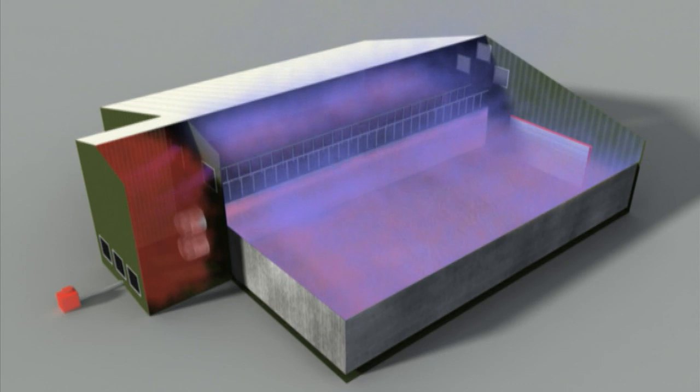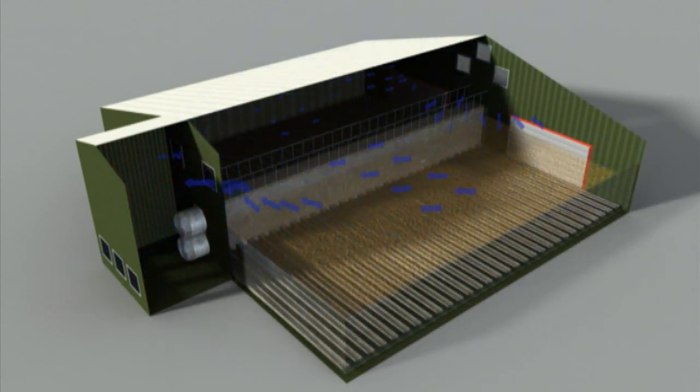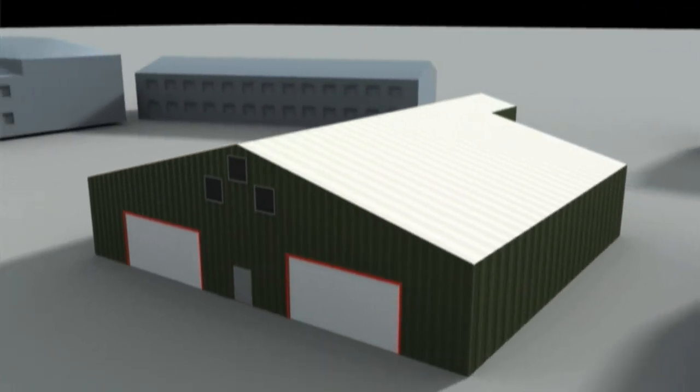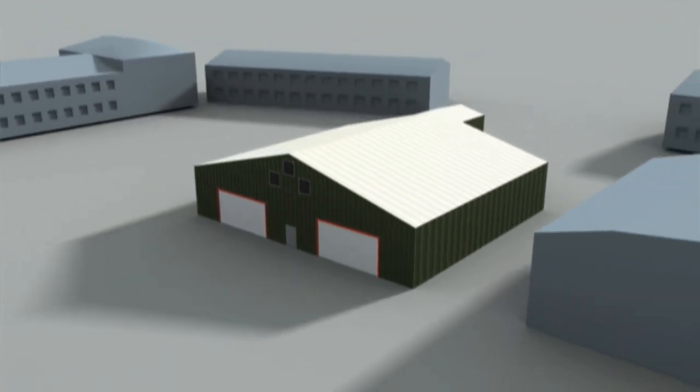Recirculation in this way should be carried out continuously until the fog has cleared, and usually takes about 4 hours. Once the headspace has cleared, the store can be purged with fresh air to control the impact of fogging on processing quality. Applied this way, CIPC usage can be reduced by up to 50%. In addition, because the distribution is managed with equivalent volumes of fog delivered into each lateral, the risk of exceeding the MRL is much reduced.